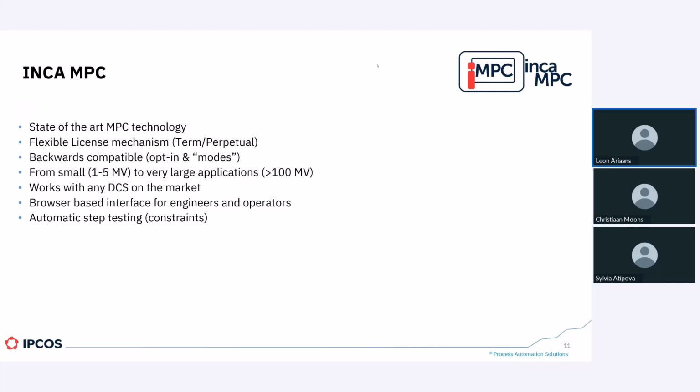You have a bit of a chicken and egg problem here. You're doing the step testing so that you can estimate a model, but you need a model so that the step testing can stay within constraints. But we're not optimizing the process, and we're not pushing it to its limits. We're only trying to keep it between constraints. So that's why a simple seed model is typically good enough.